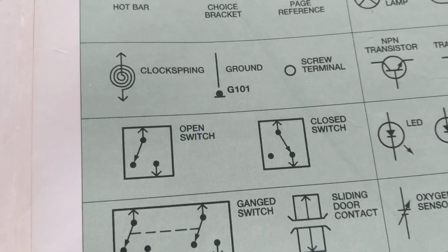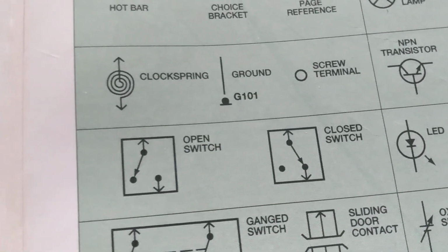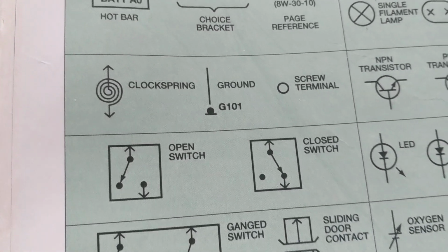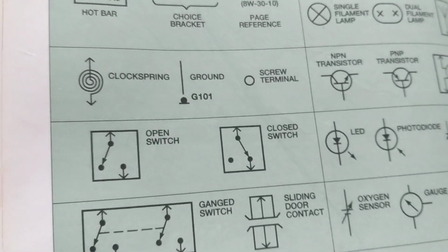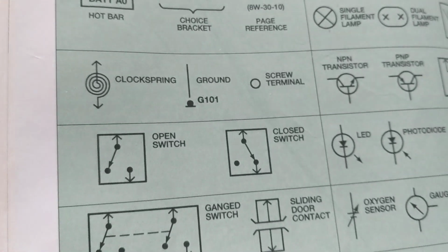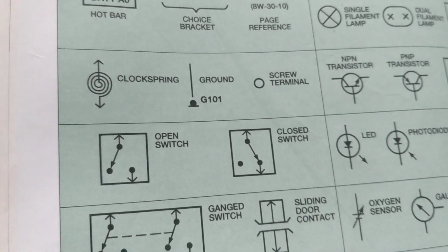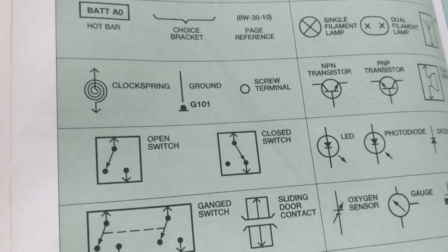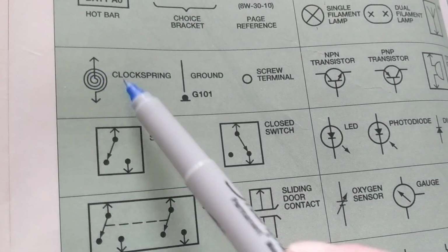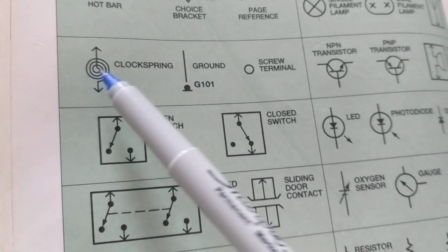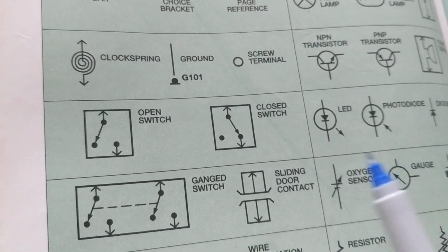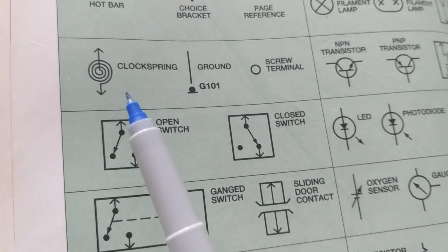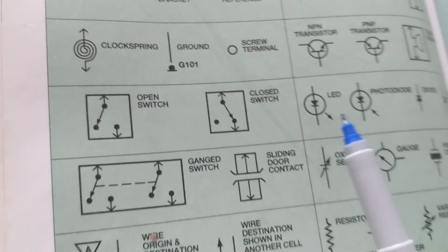Clock spring, which is a rotary device located in your steering wheel, which goes bad. Very, very popular. Which is for the horn circuits that we talked about. Which is for the airbag system. It allows you to turn the steering wheel without interrupting the electrical connectors and systems of the airbag and the horns. This is the clock spring. You see, it's a circle, meaning you could turn the steering wheel. Doesn't affect the electrical part of the circuits for ABS module, airbag module, and for the horn circuits.